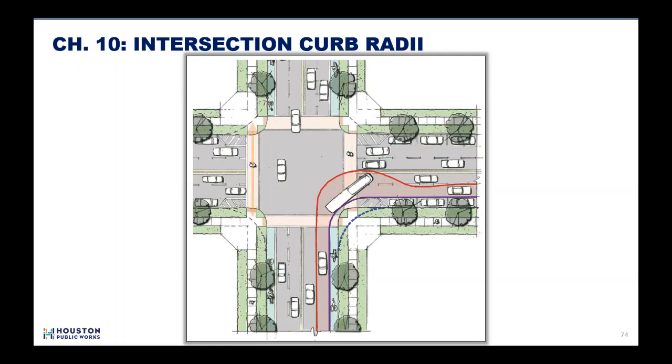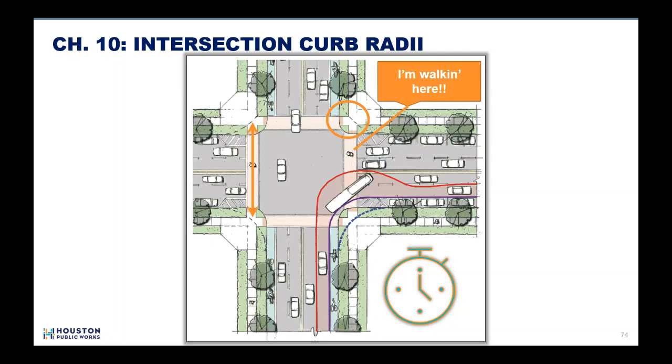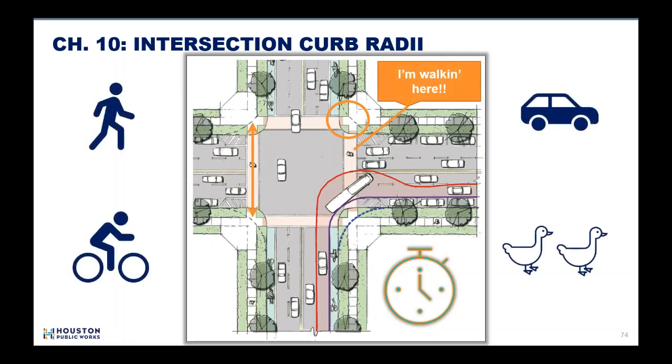You may think, that sounds good, but what are the advantages of reducing curb radii? Here are a few. They reduce crosswalk distances for pedestrians, allow for easier placement of curb ramp locations by reducing the possibility of having to make a much wider ramp to service two crosswalks, and reduce the possibility of crosswalks intersecting. They reduce traffic timing, reduce vehicle turning speeds, and increase safety for all users.